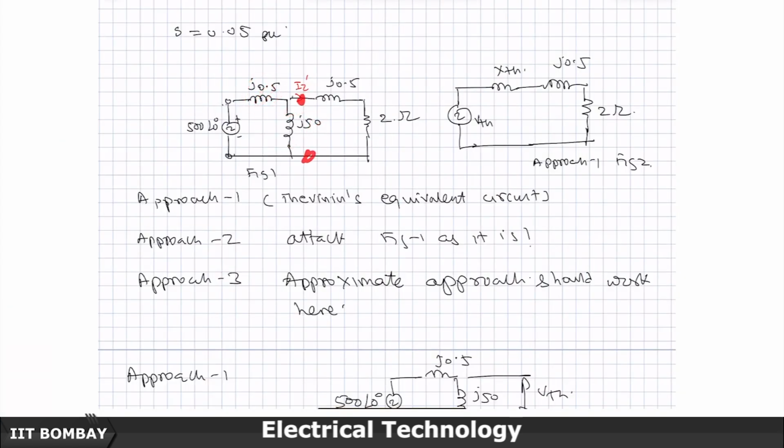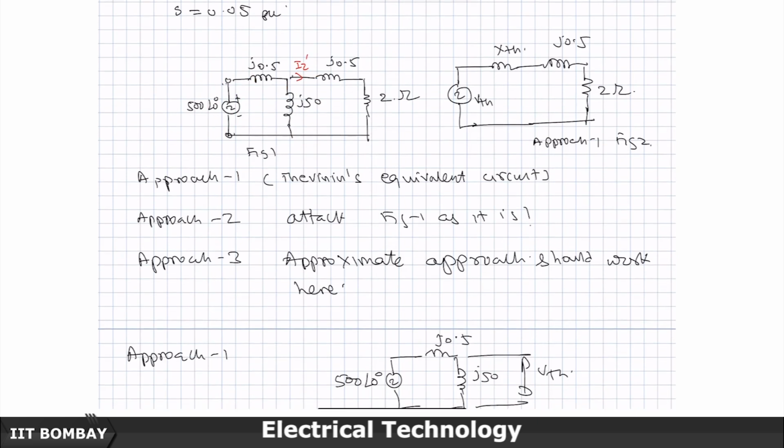So, it is correct at this boundary, but when I look at it here, I should add this current component, and the phase angle will slightly change without altering the real power, because the resistive part is only in the rotor circuit. But it will definitely alter a bit the power factor seen here. The reactive power component will be changed a bit, but the active power component will be the same, because resistance is present only in the rotor side, the load.